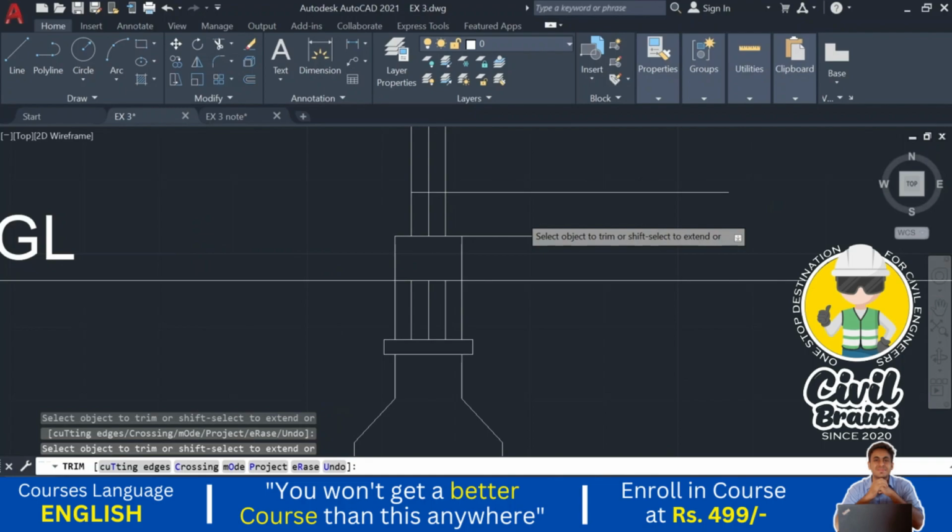Next I draw a reference line here so that using that reference line we can get the center lines easily. Now I go to the construction line and take it here, and this is the center of this particular wall. I turn on the ortho.